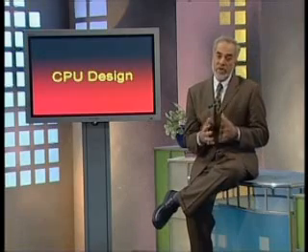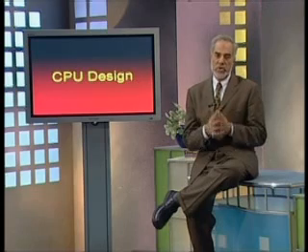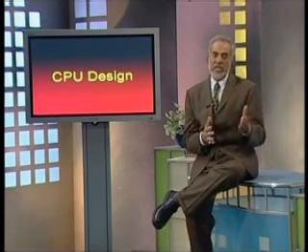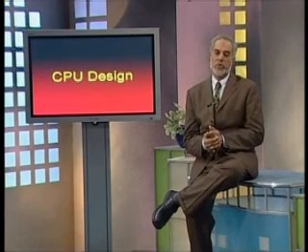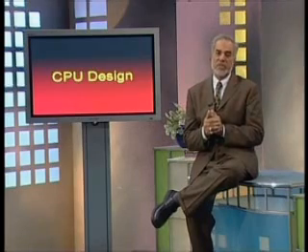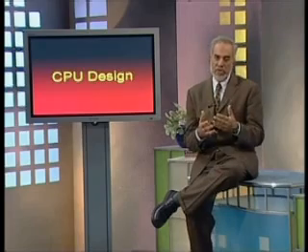So three different implementations were discussed, that is the unibus or two bus or three bus. Gradually, as we go on from unibus to two buses or three bus implementation, the corresponding logic would increase. We need to have more tri-state buffers.